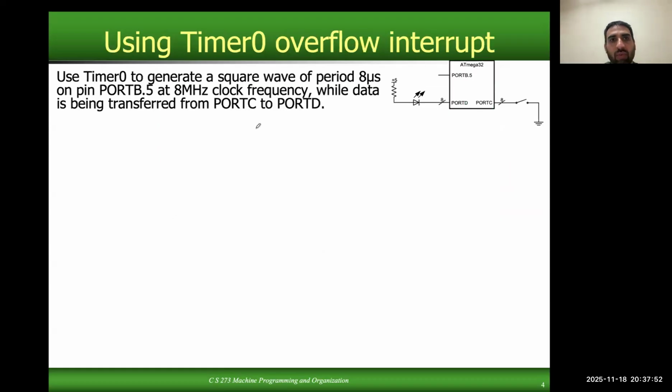Okay, now last time we were at this point, we were trying to write an assembly program where we wanted to enable the interrupt and write the ISR. But we stopped because the example code we had was not written for ATmega 328P, but for ATmega 328. Which means that the registers used were different compared to ATmega 328P, and it can become confusing. Now I have fixed the example, and we can go through it now.